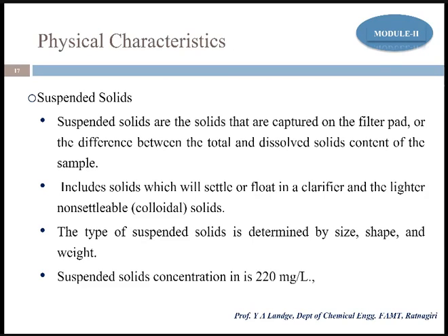If there is odor and color, on that basis we can use a certain adsorbent or absorbent which can absorb the color as well as extract the odor from it. Okay, so these are the physical treatments we need to give before sending it to the secondary treatment. This is very important. All the matter needs to be captured at the initial stage in the physical treatment. Okay, so this is all about the physical characteristics.